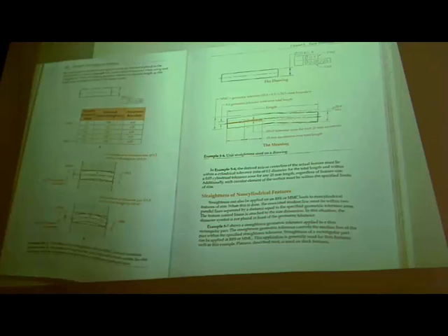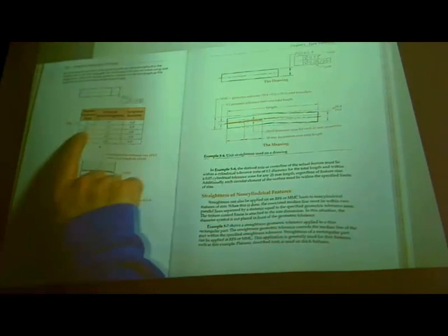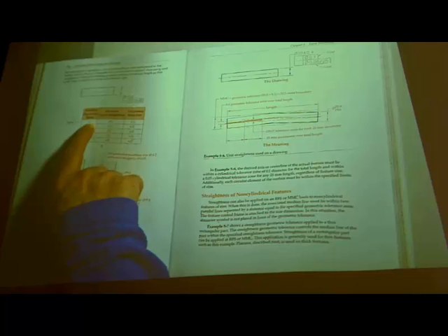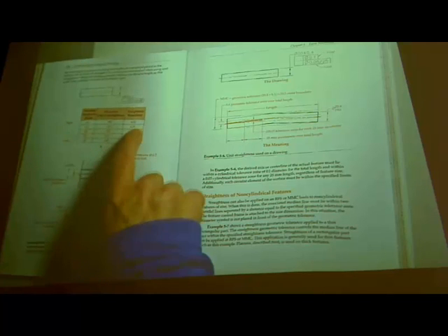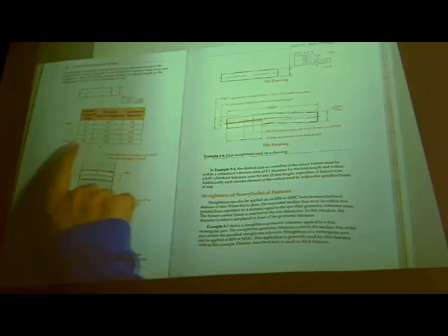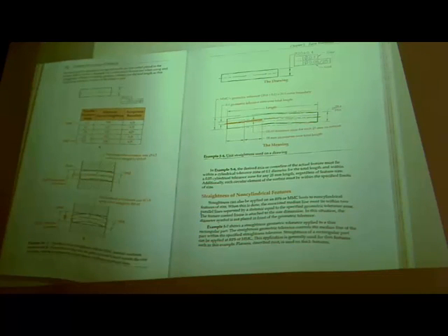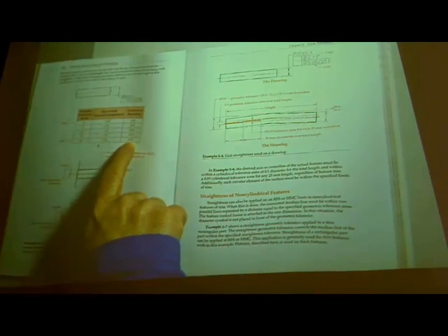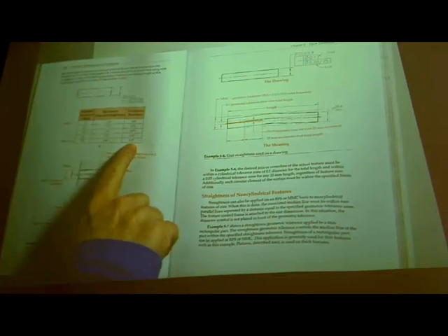So 6.2, so if we produce at MMC 6.2, it's at 6.25. So you can see the virtual condition stays the same. But considering it as a cylinder, a round part, an envelope that has to accept this part, the mating part is actually going to have to allow for this virtual or acceptance boundary.